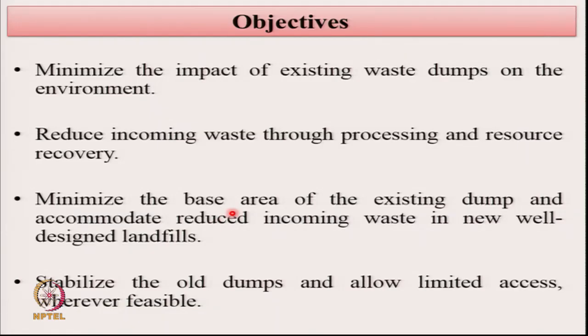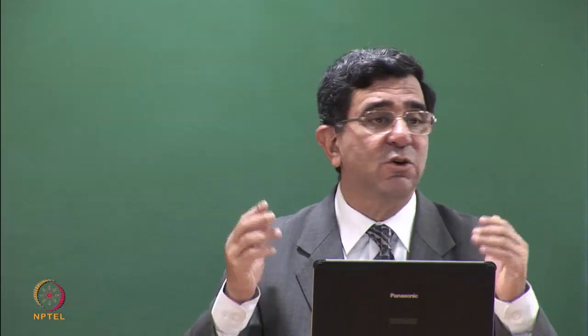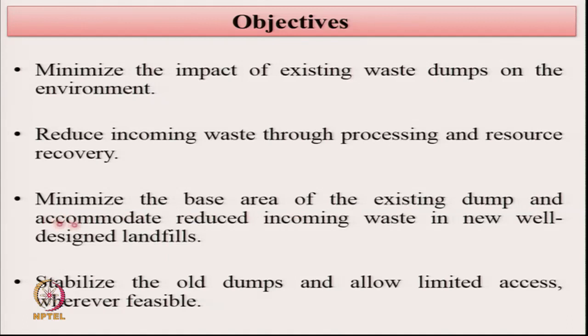Minimize the base area of the existing dump. We saw many of the dumps are between 0 to 10 meters high. Well, that's not an efficient use of the area. We are saying from an aesthetic point of view, you can have a dump which is 15 meters high, and if you really are short of space, you can even take a dump higher. So you have a 10-meter high dump, you are using double the area. You make that 20-meter high, you can release half the area. So minimize the base area of the existing dump to accommodate reduced incoming waste in new well-designed landfills.